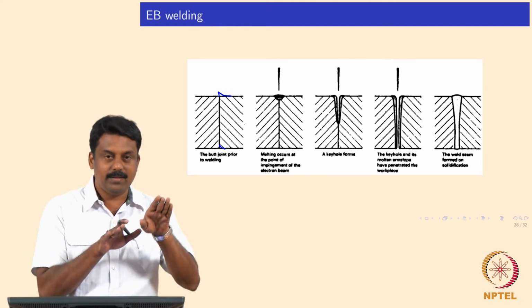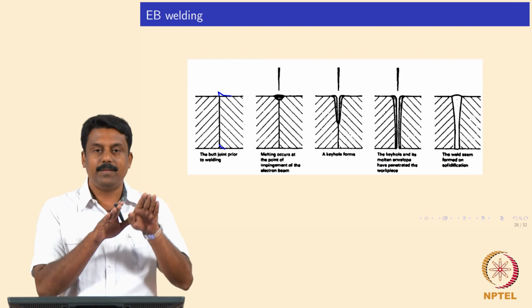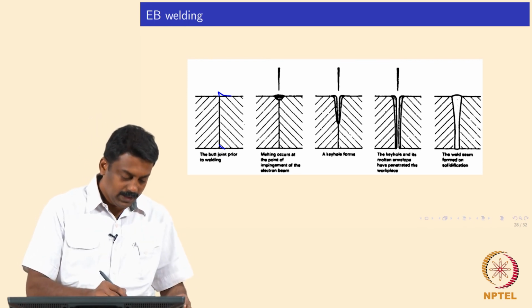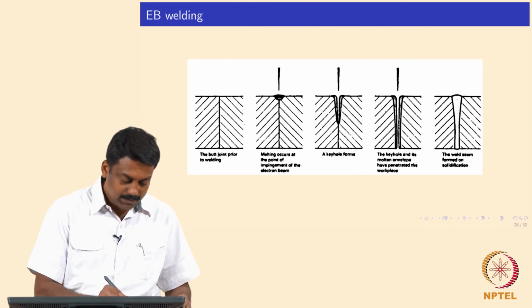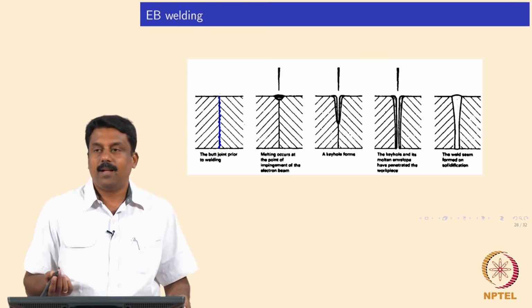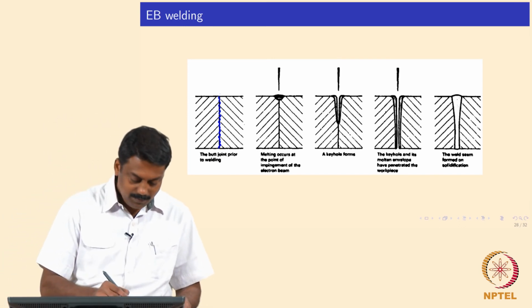Okay. Because if it is not fit up properly, if they are misaligned, then you are not going to make a joint. Similarly, the surface preparation, the roughness. If it is not done properly, it is also not going to work out, right.